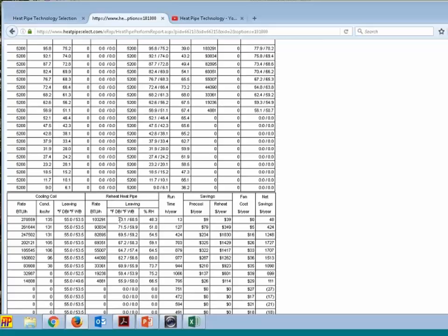So what I'll do is I'll start scaling back performance. 71.5 at the second. I'm still not using any terminal reheat. It's really only when the outside air temperature is around 82 or 76 degrees is where I'm actually starting to use some sort of terminal reheat. And again, that's less terminal reheat than the 2-row example.